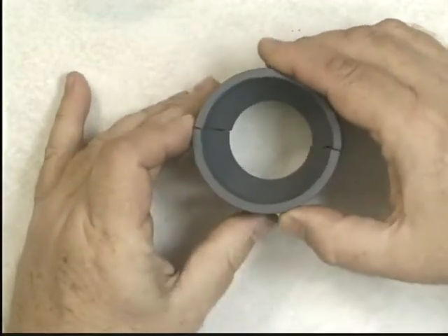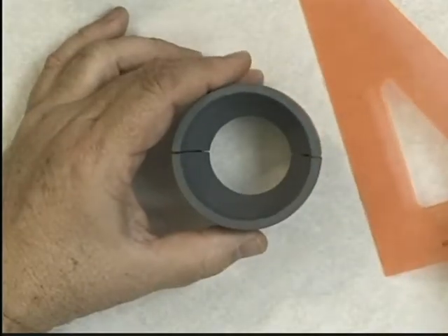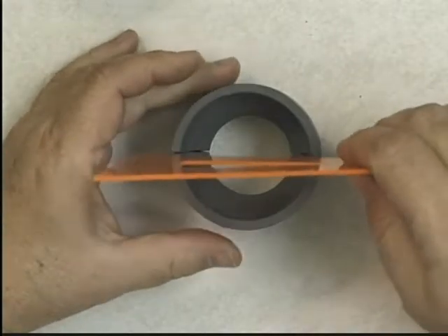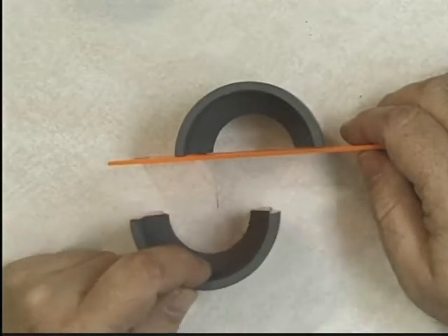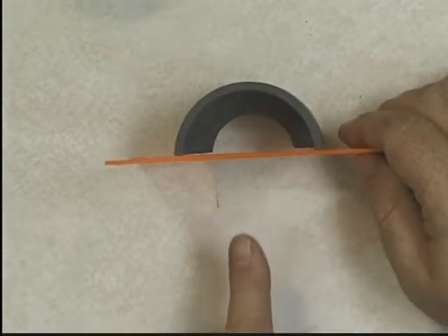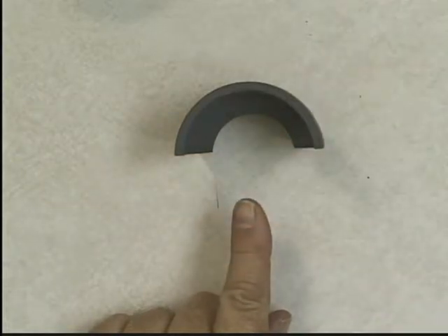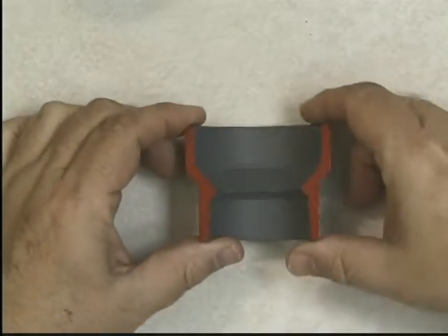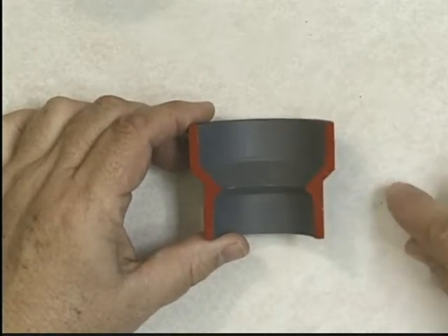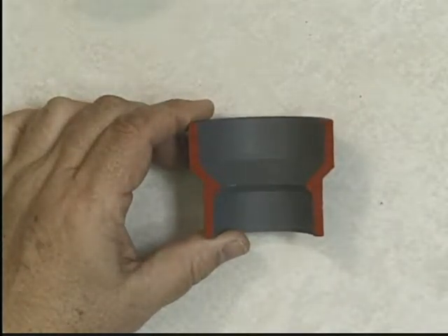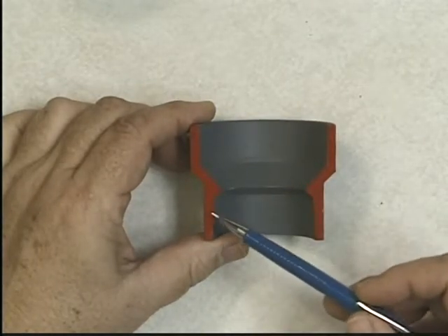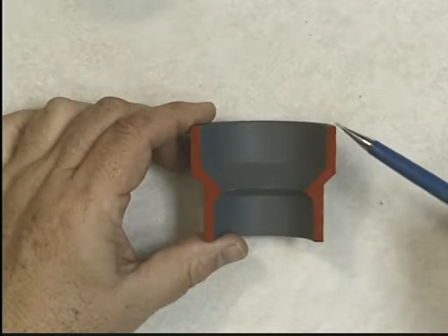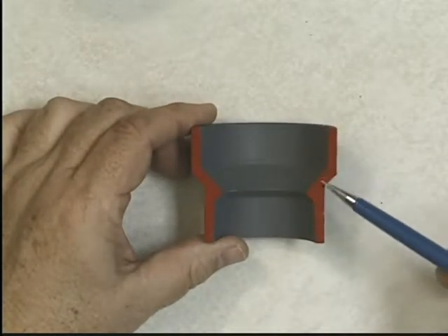Now let's pretend that I'm going to, again, take my triangle and simulate the cutting plane. Let's pretend that I'm going to cut right down through the middle of this, and then I'm going to take this part of the material away, and I'm going to look in that direction to get a section view in the front view. And you see the interior is now revealed, and once again I believe you can see that I've colored in red the part of the material that was in contact with the cutting plane. And once I pretend to remove the part from the cutting plane back towards me, the interior is revealed.